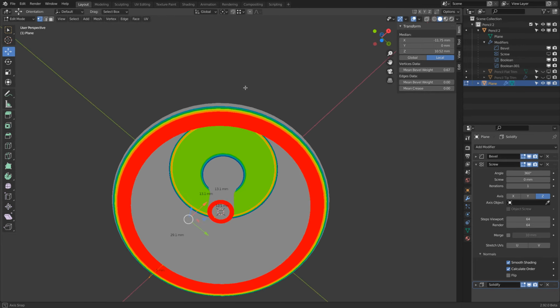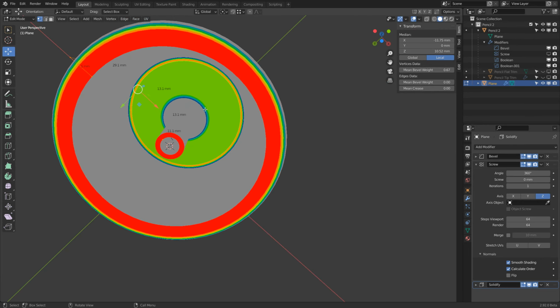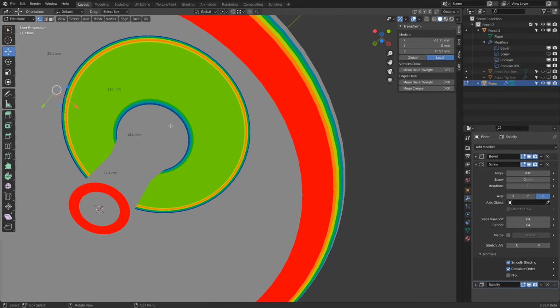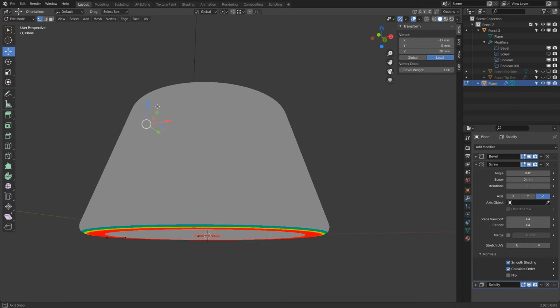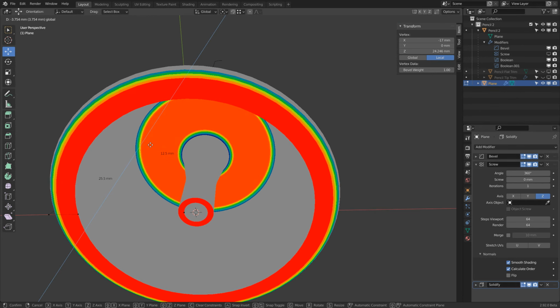And 3D printers, they can only tolerate an overhang to a certain degree. So nothing here is really, besides there's a little bit of orange. So it's not ideal, but actually this will be good. So when we select this point and then move this up, let me see how this goes away. So perfect. And then here we have more overhang, and then yeah, this is an overhang that's not printable, because all the plastic would just fall straight down when it would be squeezed out.